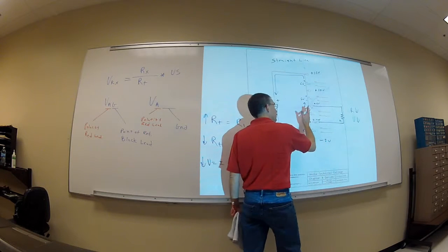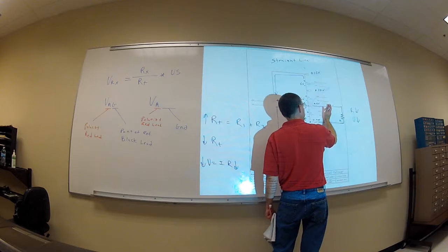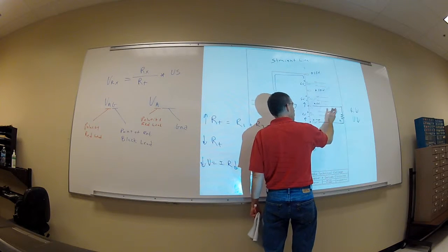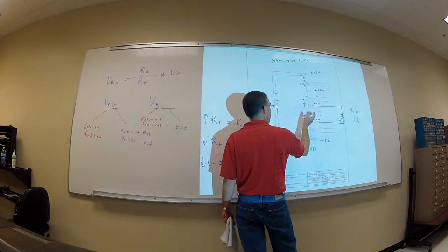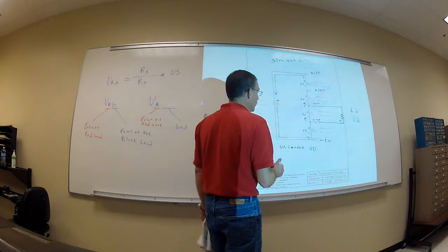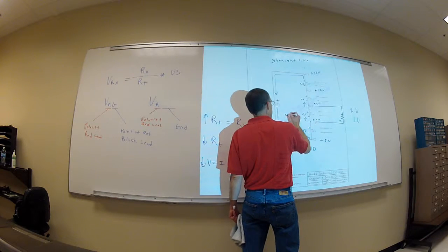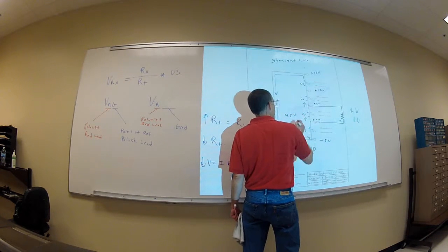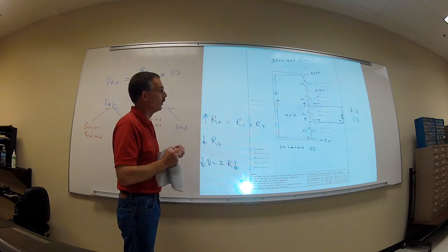And all they want you to do in the further investigation is put a load across that circuit. They're just going to have you put in some kind of resistor, and you're going to load it down until this drops by about 10%, I think is what it is. So when you see that voltage drop across R3, for example, drop down to 4.5 volts, you know that you went down about 5% or 10%.